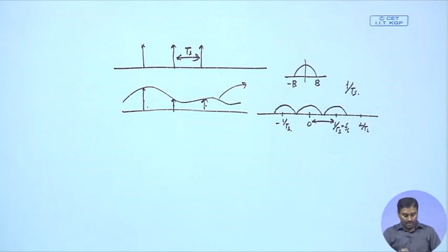Okay. So, this is what happens. Whenever we sample, we want to reconstruct the signal. That was our target: if we sample it, we should have a provision to extract the signal. It is similar to modulation, where we must have some mechanism to demodulate so that we get the original message signal back. Here also we are trying to do the same thing. With an impulse train doing pulse amplitude modulation, we need a mechanism which takes my signal out undistorted.